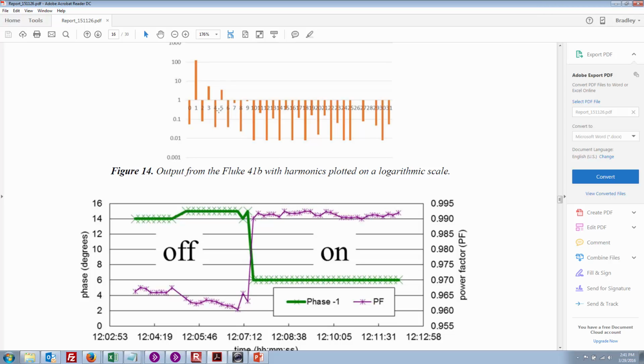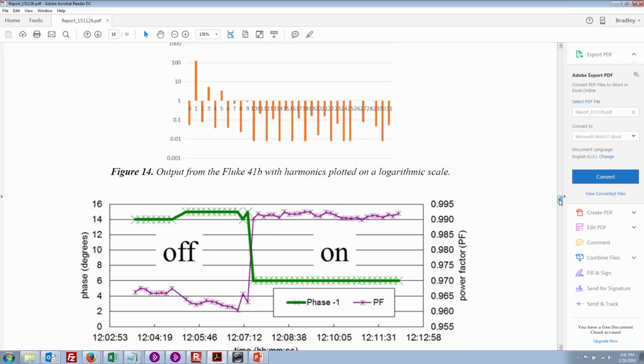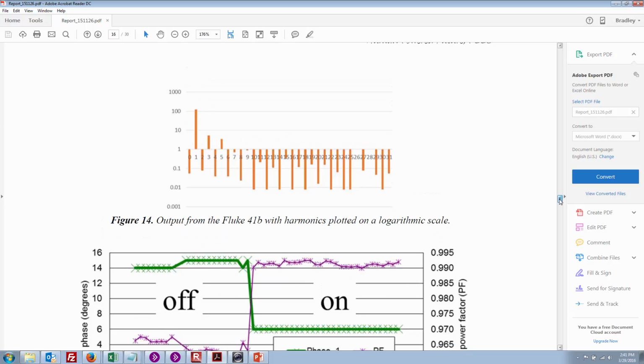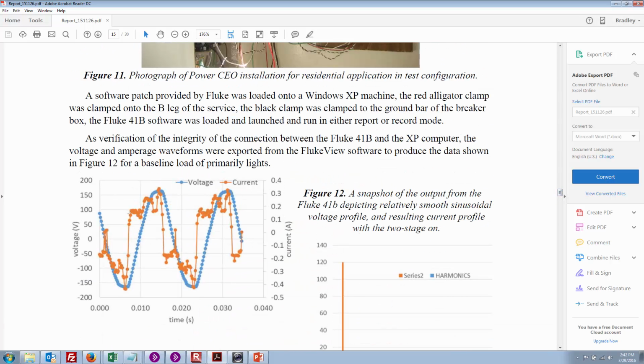These are the fundamental harmonics involved. Every single 60 hertz wave, this is basically your 60 hertz right here. This is your 120, your 180, 240, etc. There are all these different harmonics sitting out there. This is DC. They have different strengths and comprise the overall waveform, which can be quite complex. The voltage is never a perfect sine wave. It's always looking a little bit funky depending on what's coming in.